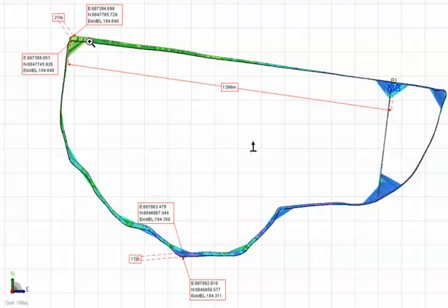Now, the difference is that Trimble field level system uses a local plane coordinate system, which is slightly different to the other coordinate system, which is UTM, eastings and northings type thing. So you can see it's 21 meters difference there, and on this southern edge it's 17 meters difference.